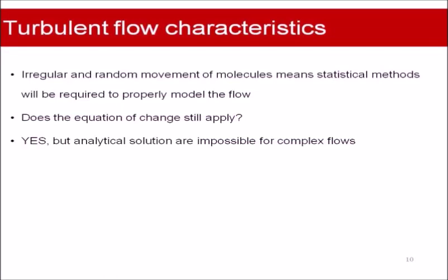Because of the highly fluctuating nature of the flow, statistical methods such as time averaging are applied to the equations of change when the flow is turbulent. But analytical solutions are not possible, so numerical methods such as computational fluid dynamics are used to get solutions when the flow is turbulent.